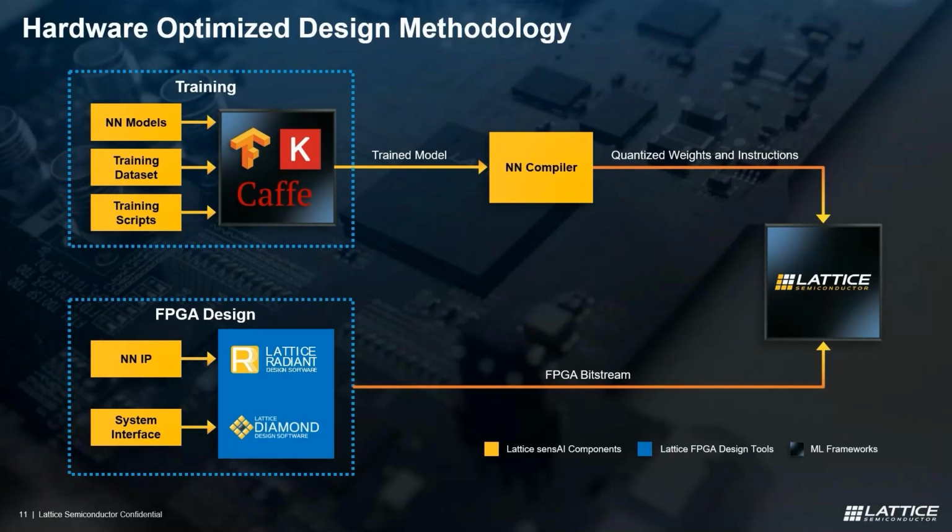We are discussing the Sense AI solution stack, and in terms of software tools, for training, you can train your models using TensorFlow, TensorFlow Lite, Keras, or Caffe machine learning frameworks, and then compile the trained model and generate weights and instructions. And depending on which target FPGA device you select, you can use either the Radiant or Diamond tool and generate your bitstream and program the FPGA with it.